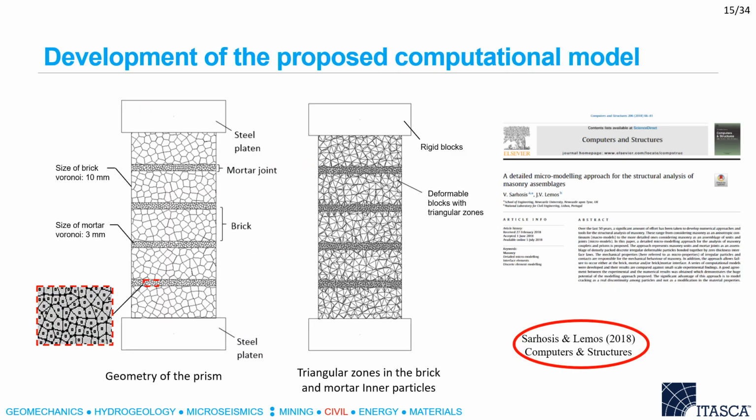In the numerical model, platens were modeled as rigid blocks. Bricks and mortar were discretized into inner particles and modeled as deformable elements. A low velocity was applied at the top of the platen to ensure a quasi-static condition. Vertical load was estimated using FISH programming implemented in UDEC.